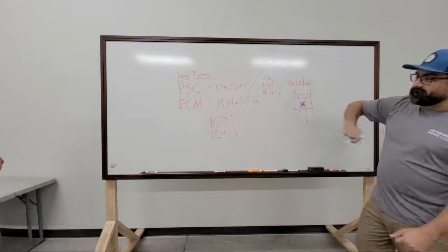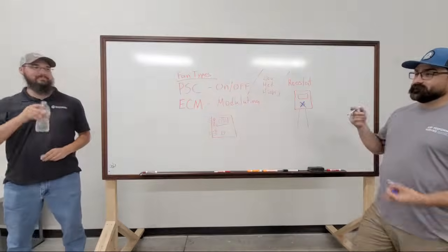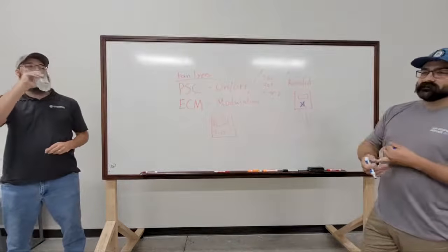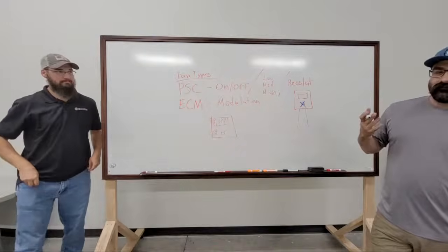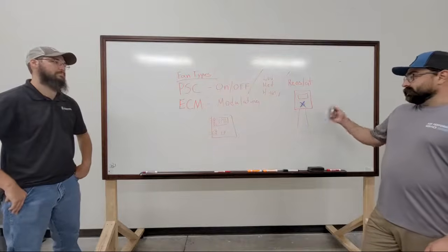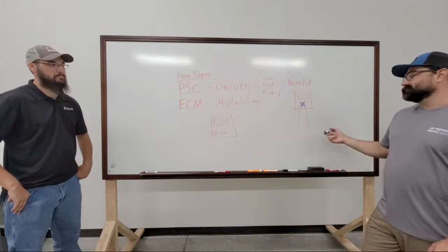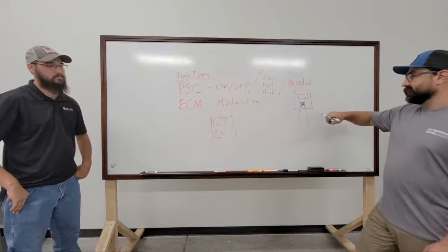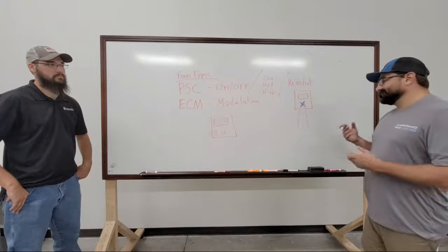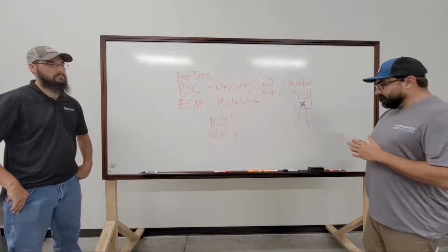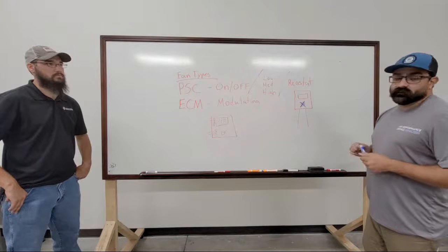So if this ever has to be replaced, it's where it gets complicated, because you need to know what kind of flow the box is doing. You would need to know which grills are served by the box, and then you would need to calibrate that fan speed based on those air balance calculations. Also, if the motor changes, those need to be reset. So typically, if a motor changes by itself and you're not dealing with a burnt up rheostat, I wouldn't bother messing with it, but technically it should be reset. But to get it there without the proper tools is highly unlikely to get it back to where it should be.